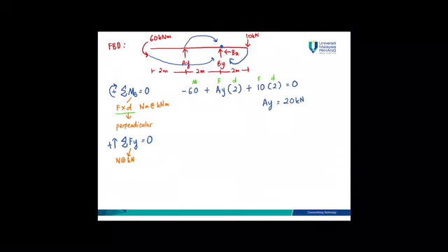You just take the Newton or kilonewton for unit. Start with summation Fy. We already get the AY value, which is 20 plus, because it is upwards, BY, and then minus 10 kilonewton because it is downwards, is equal to 0.